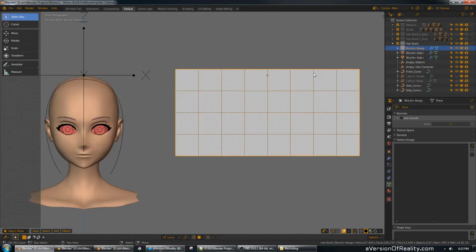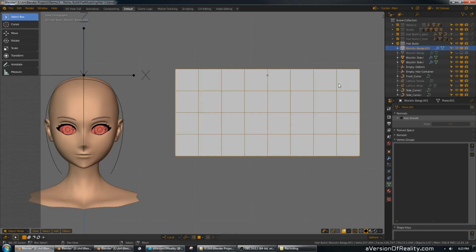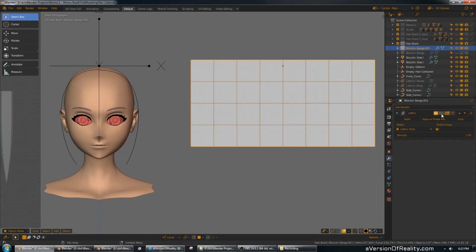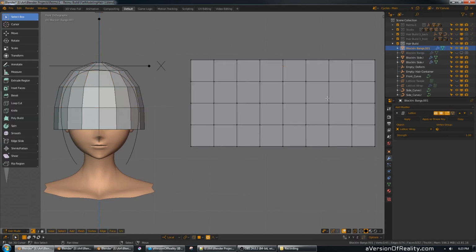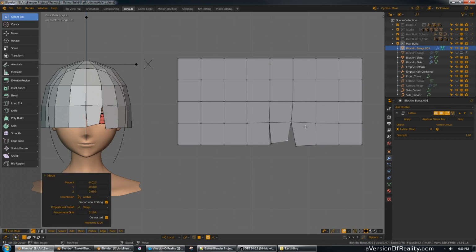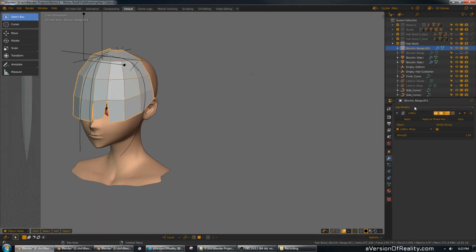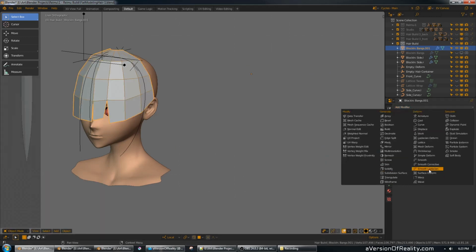The one could just be editing our block-in plane. Copy that, have a backup, and of course that goes into our lattice cleanly. But we could do things like grab some of these points and rip them, make a few different strands, do some proportional editing. You get the idea. And then chuck a solidify modifier on it.